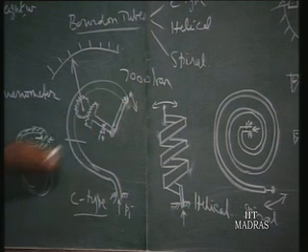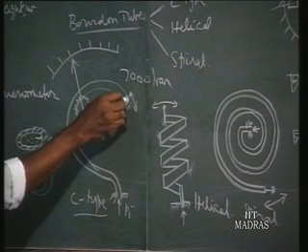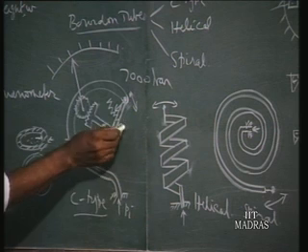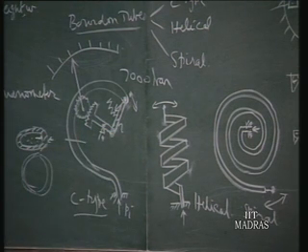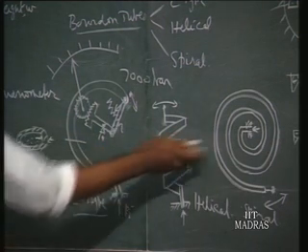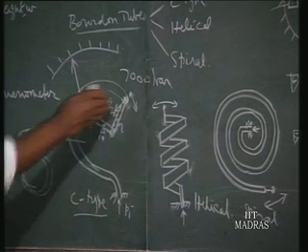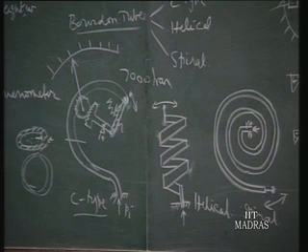So like this, whatever we have shown, you can have a linkage mechanism for reading static pressures. If there is any dynamic pressure, we can connect a wiper and convert this wiper motion into an electrical signal using a potentiometer transducer, and then we can process it. That is also possible in this type. If we convert this motion into an electrical quantity, we can use it for slowly varying dynamic pressure signals.